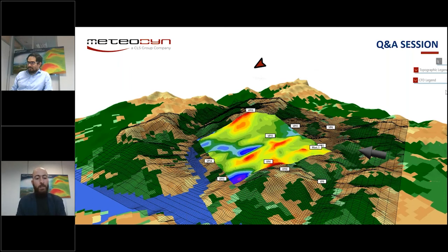So this is what we use for wind studies, and what we recommend to all the users, okay, for the CFD computation. But of course, this is always a compromise, okay, between the performance and the precision. So it depends on your machine, what the RAM of your machine is, and of course the size of the site.